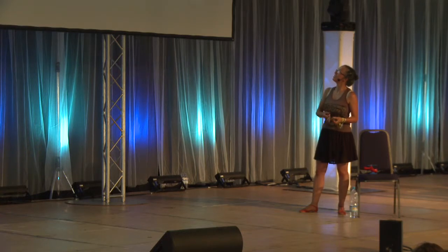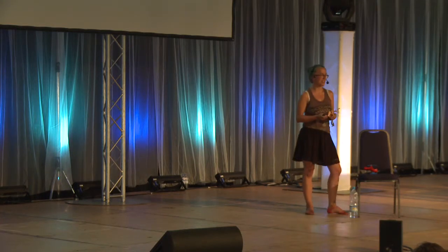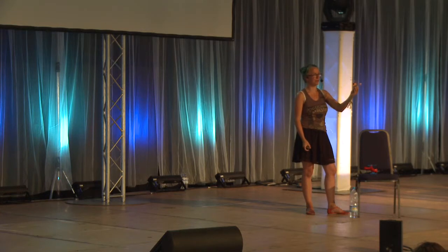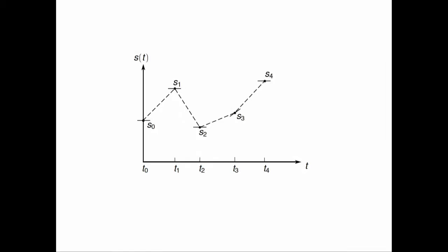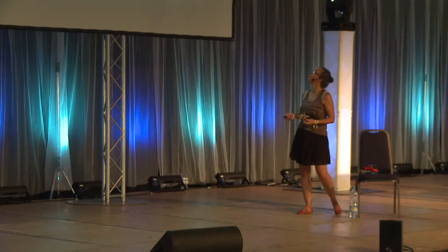Before we come to how we do that, to the control part, we have to define one last thing, that is the actual path we want to fly. So you want to hover, so you start, you hover, you fly around. So what you do now is you define your path as a cubic function where you say, okay, my starting velocity and final velocity is 0. It's nice if it's 0 at turning points because that makes it nicer mathematically. And we say, if I have an intermediate point, this velocity shouldn't be faster than half of the sum of its neighboring points, so something pretty nice to follow.